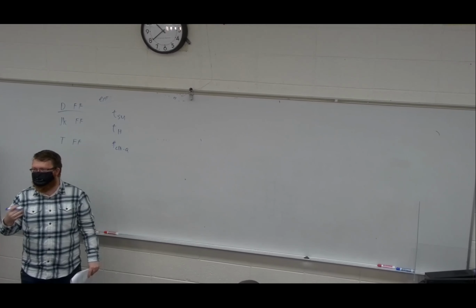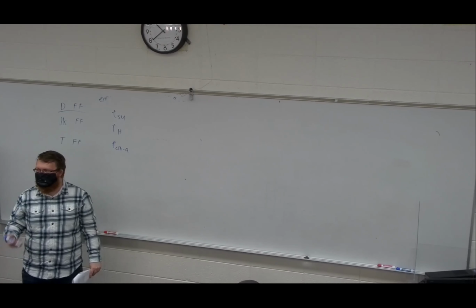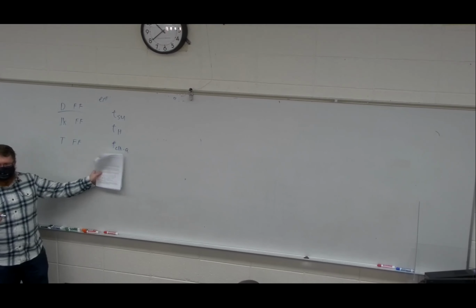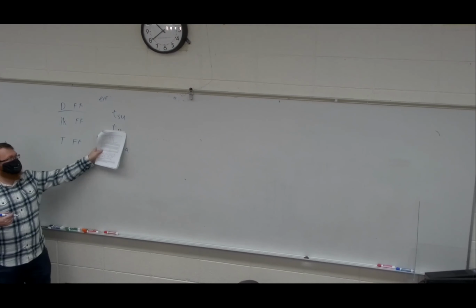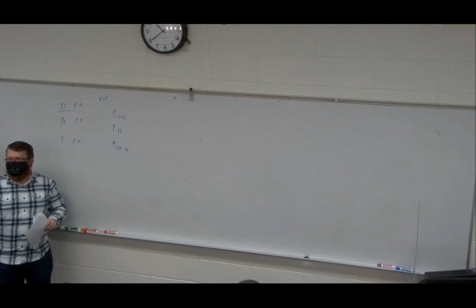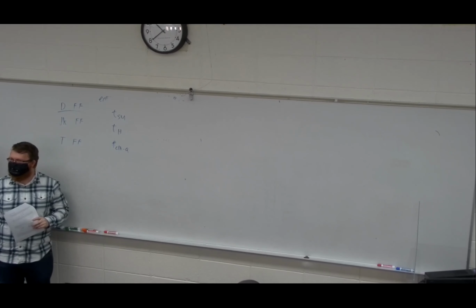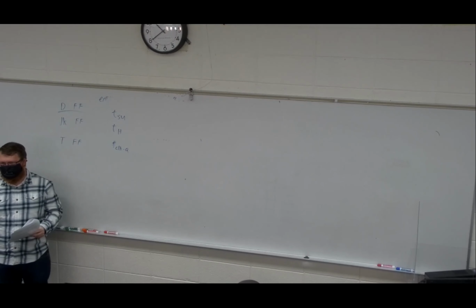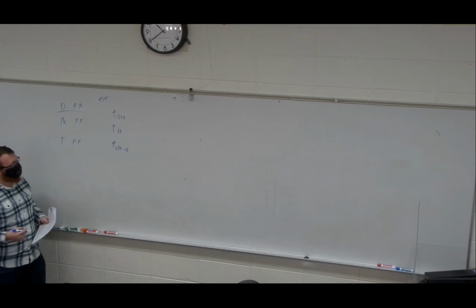Because if the clock happens at the exact same time as we change data, we have no idea what's going to appear at Q. So it has to be set up before that. Similarly, if the clock happens and then we change it immediately after, it may or may not hold that value. So we have to have a hold time after the clock hits.